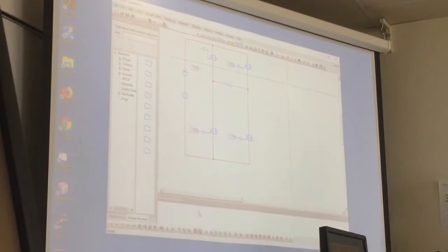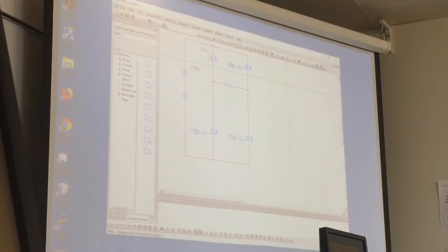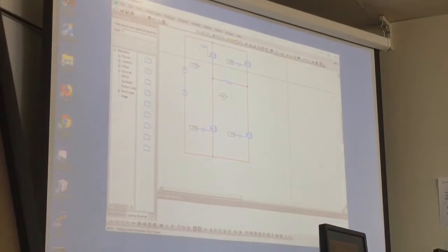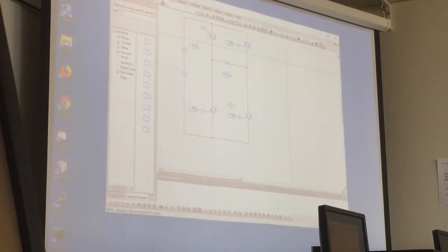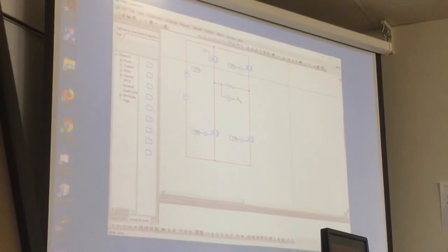Okay, so guys, for the voltage probes, we have two options. We can have, let's say, an isolated probe. For this, you have 2 points. You can take from whatever you want. Let's say I want to see the voltage in my load with this voltage probe. I just need to connect that in parallel with my load. See?